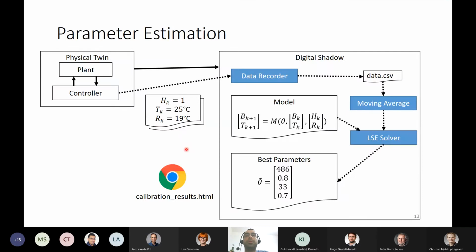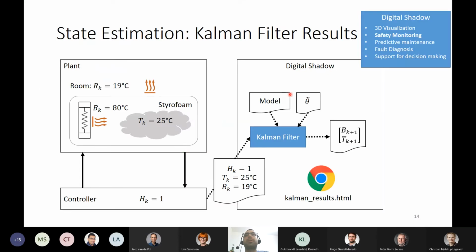It means we have a good model of our system, which we then can use to work with a Kalman filter. The main difference, I have to stress, between the model and the experiment we've made so far and the Kalman filter is that the Kalman filter will continuously take measurements coming from the system and will continuously take them into account when trying to find the value of the missing state and predicting the next state. The model that we just did, we just were lucky because we started the simulation of the model at the state of the system that we knew.